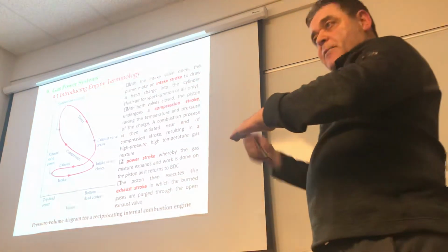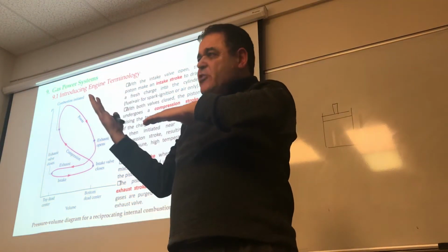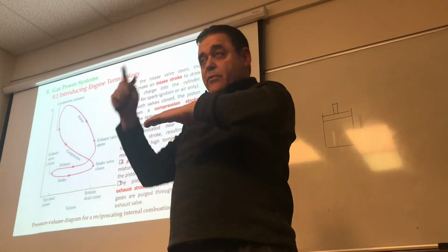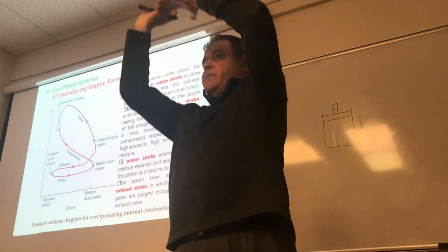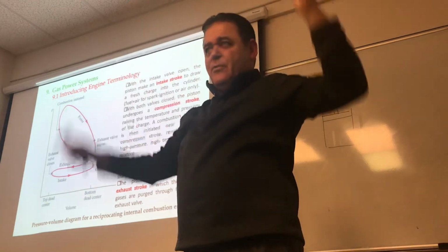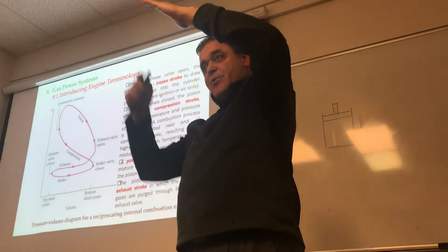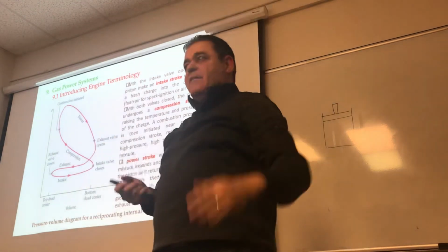Then what happens now? When the piston is down there, what's inside? It's just combustion gases, right? Combustion gases that are worthless to you. So what do you do? The exhaust valve opens, right? The piston goes up and it rejects all those fumes, right? And then the exhaust valve closes, then the intake valve opens again, and you're repeating the same stuff, okay?